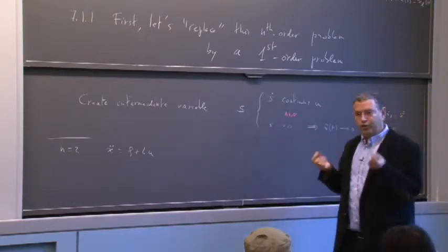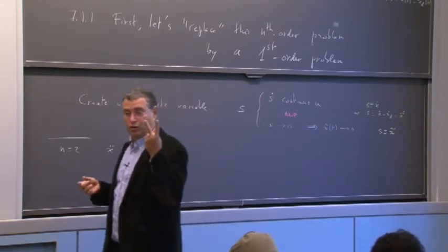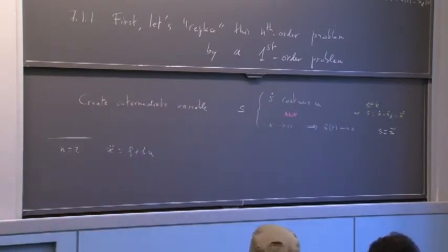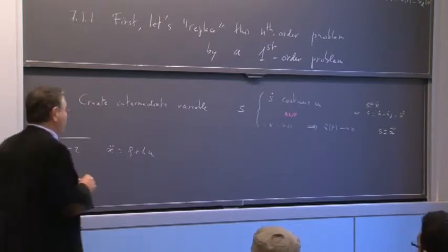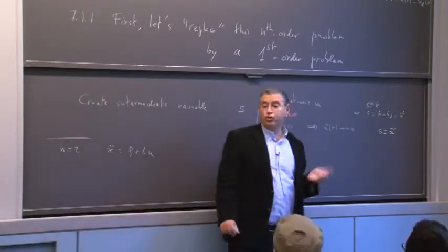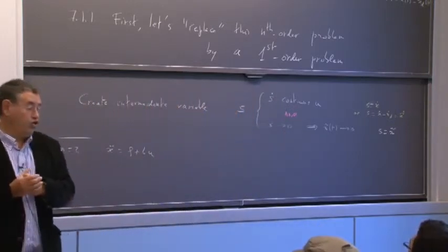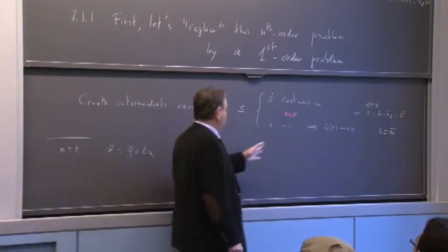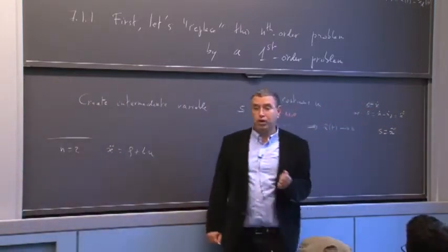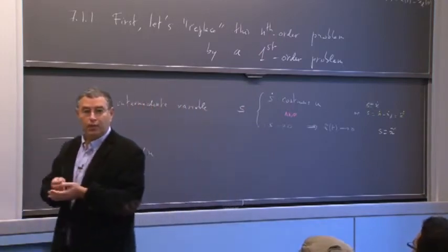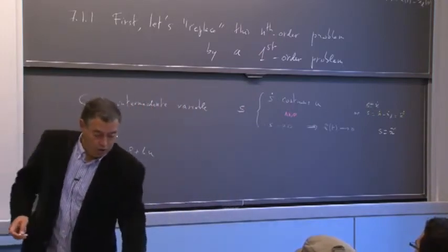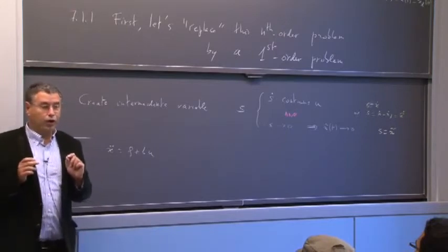So in other words, we're trying to find an intermediate variable that verifies two conditions that we need to differentiate only once to find the controller, like x dot in a second order system, but also such that if we somehow control it to 0, we have the original goal achieved, namely that x tilde tends to 0, like picking x tilde directly. So neither of these works.